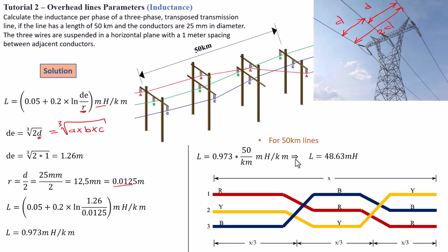So you can basically include some series capacitors. The addition of series capacitors or shunt reactors will actually act as compensating devices in your transmission line to basically maintain the voltage stability. So that is very important to take note of as a power system designer.